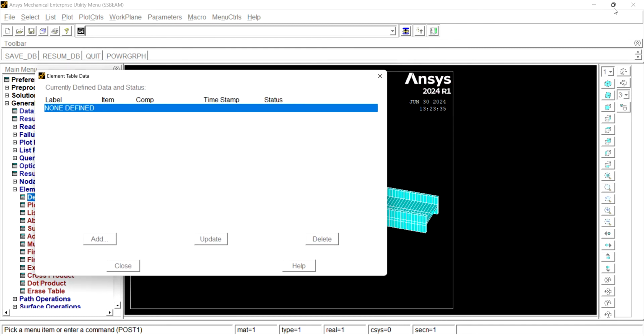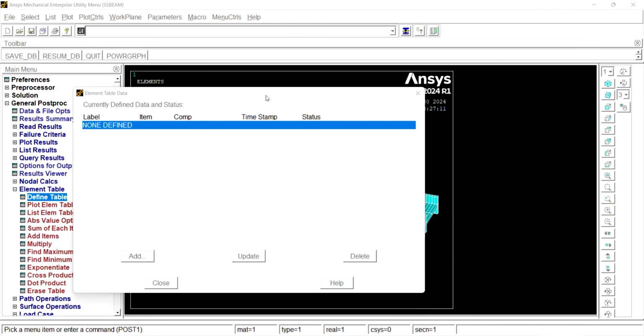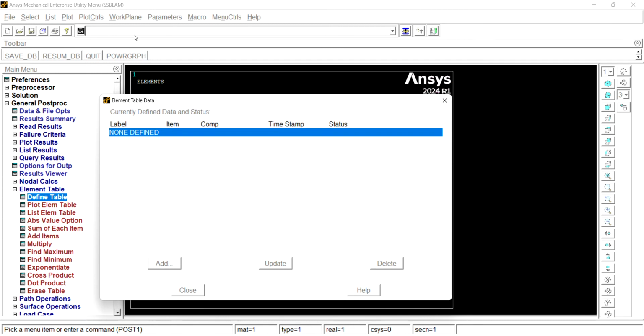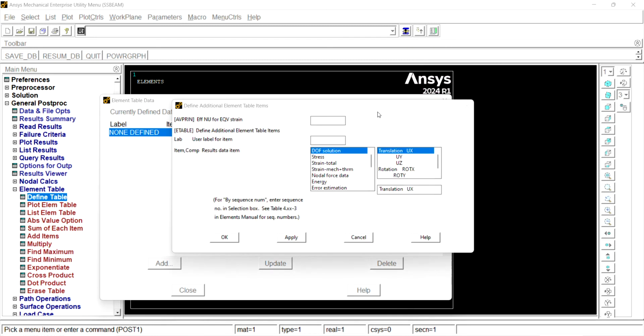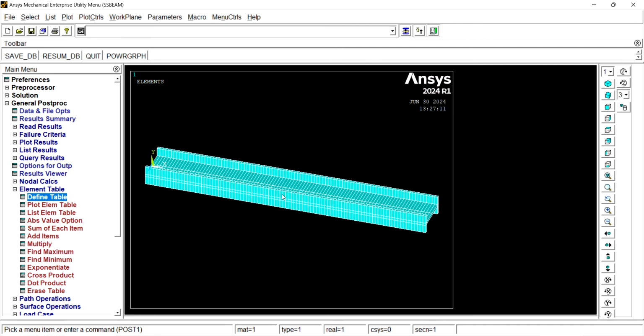Very weak software. If you mistakenly selected that, close that error first, then that window is hidden. To get it back, you can use this raise hidden option, and that window will come. So first you have to cancel this, then only you can close this. Otherwise, if you don't know, you have to close the software.